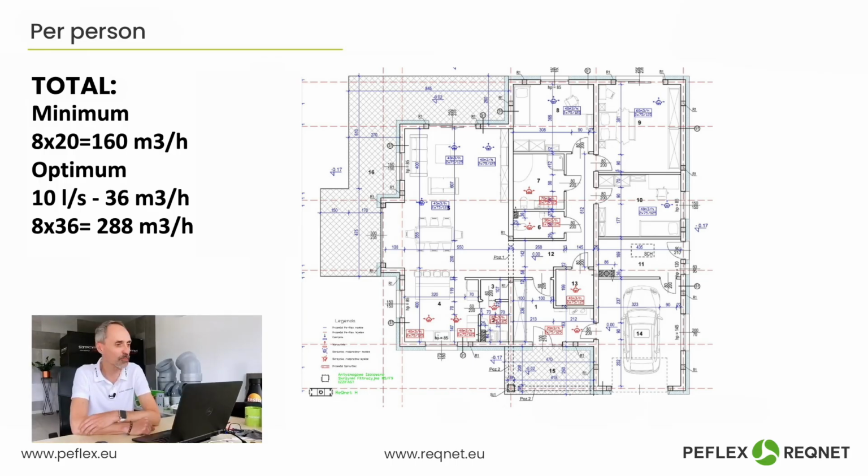So, taking into account the regulation of the Minister of Infrastructure, the regulation regarding technical conditions, we have paragraph 141.1, which states that the flow of outside air supplied to rooms that are not workspaces should be based on the flow of exhaust air in accordance with the applicable Polish standard, but not less than 20 cubic meters of air per hour per person expected to stay permanently, as specified in the construction project. But what does that mean for us?